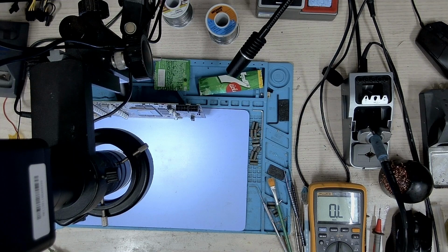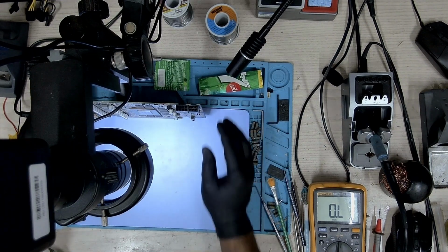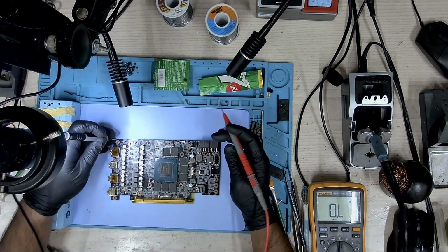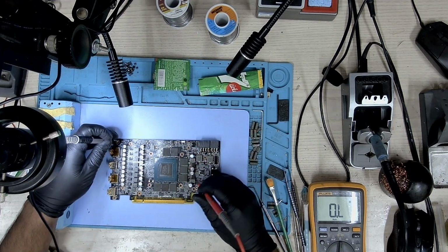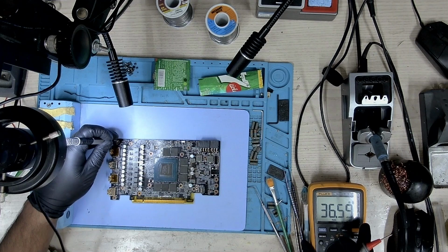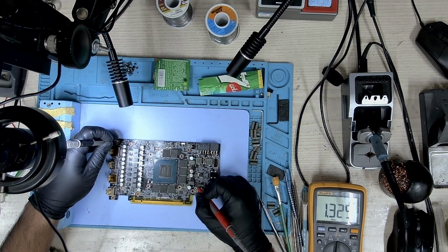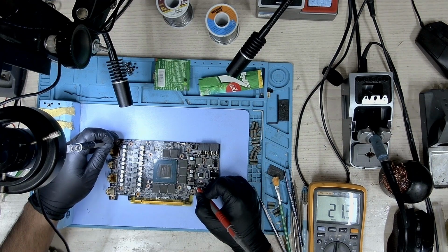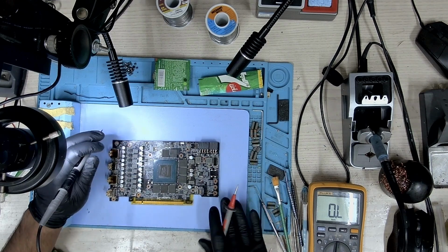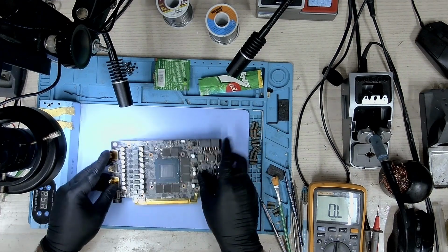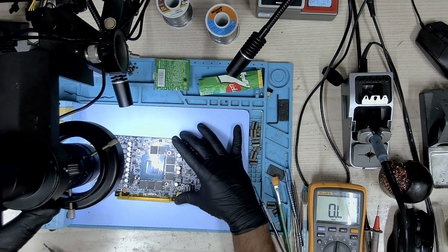Okay, so the card has cooled down, and we will do a resistance check. Hope you can see. So about 21 ohms. It's decreasing because the air is still hot. Okay, so we don't have a short. What I'll do now is proceed to change the straps.